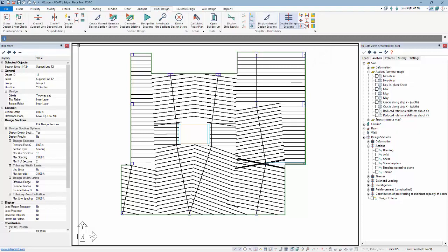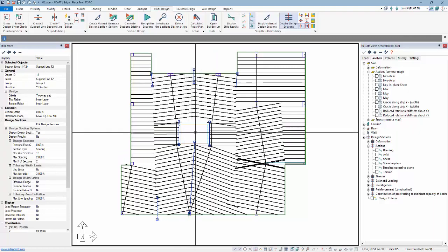So if I go to floor design and I turn on the splitters, we have a few splitters here bounding the outsides of this opening so nothing crosses into the opening. You'll notice I actually removed that wall, that inner wall, and just stretched out the opening. That was also something that I did to clean up this model in terms of the meshing. That inner wall wasn't absolutely necessary in a single level floor, so we modified that particular region of the floor.